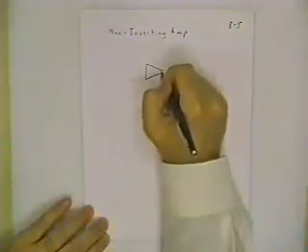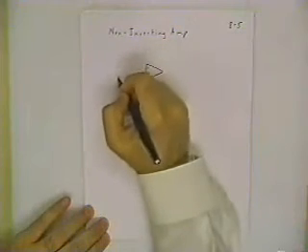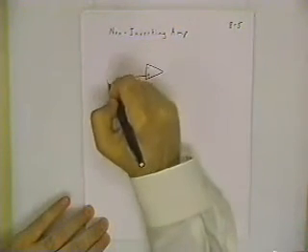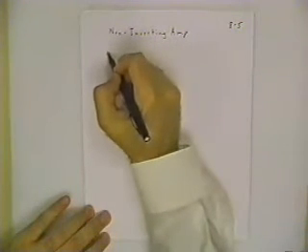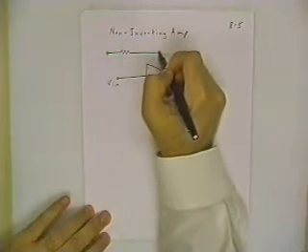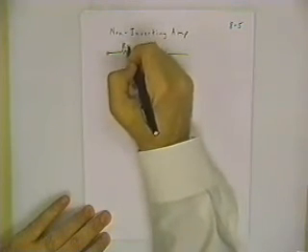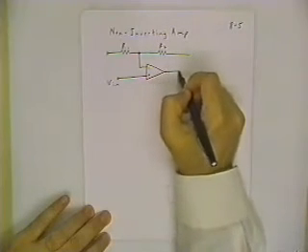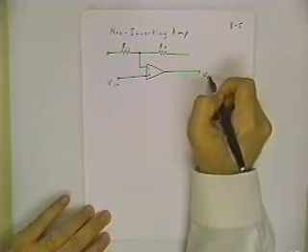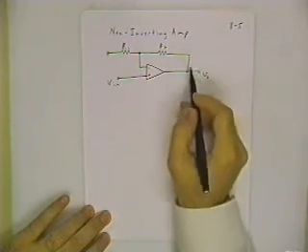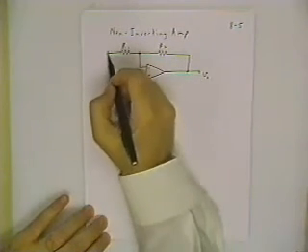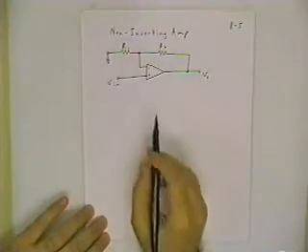Well, next circuit I want to show you is the non-inverting amplifier. This time, instead of grounding the positive terminal, I'm going to bring my input signal into the positive terminal. So there's Vn. I'm going to have my same resistor ratio or resistor network, R1 and R2. And there's my feedback path again through R2. What I need to do with this terminal is ground it.